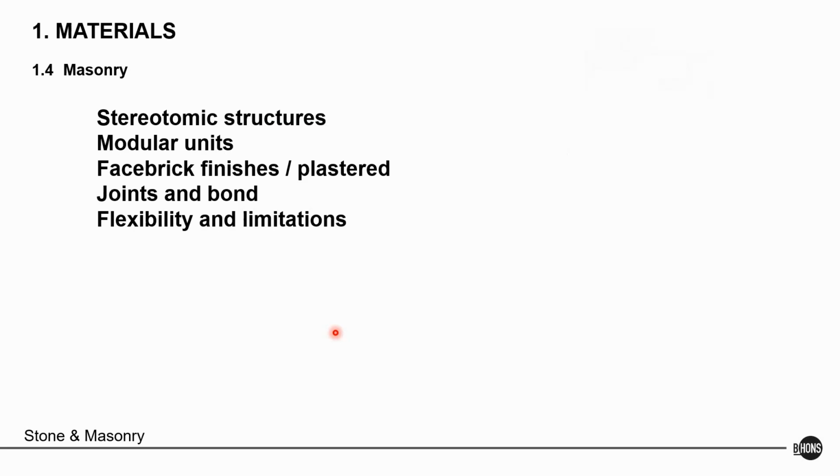So remember that we use brick force to ensure that they are strong enough. The brick force is actually like steel reinforcing. We put it every 5 brick courses, we lay that into the joint and ensure that there's some tensile strength for that wall.